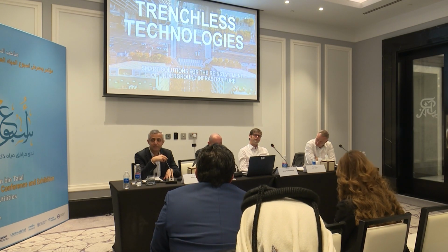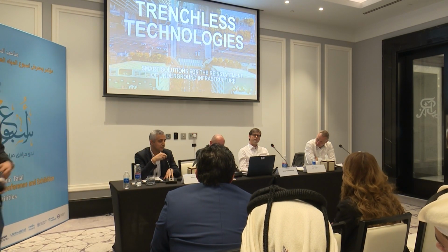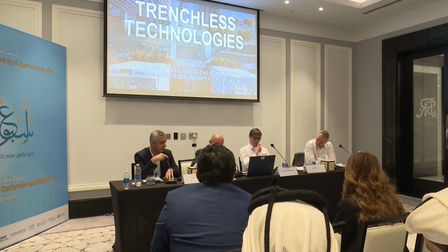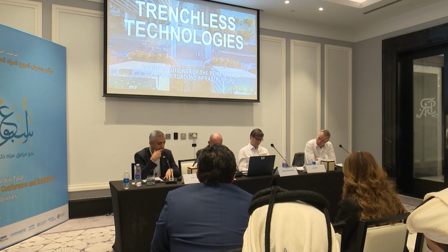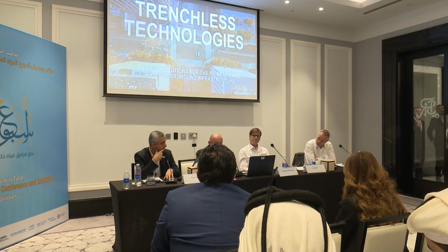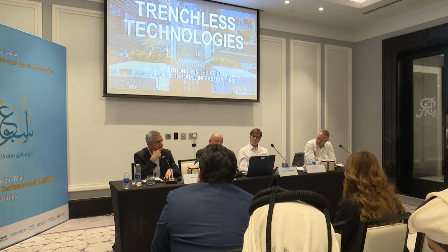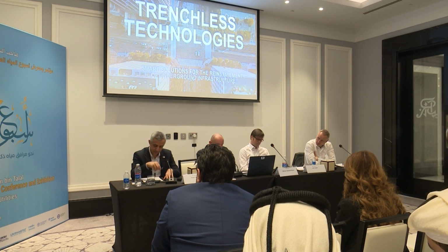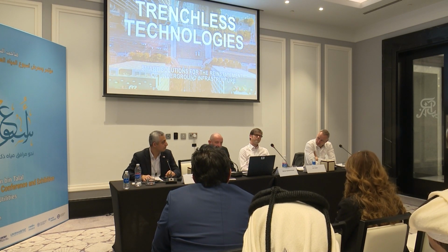About the earthquake, the CIPP systems have actually developed in Japan, and nowadays we have a factory in Japan, actually 2 factories, and we produce especially for earthquake protection. That means their liners are designed differently, they are stronger in the wall thickness. There's a standard in Japan for earthquake of CIPP glass fiber reinforced UV liners. And they use it constantly as a program to refurbish existing pipes.